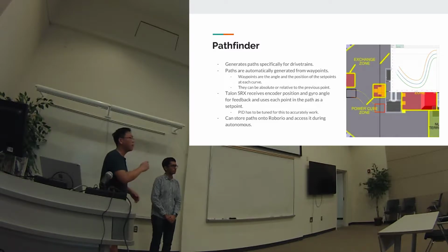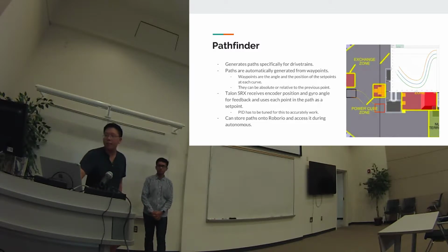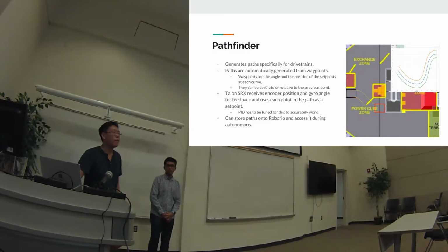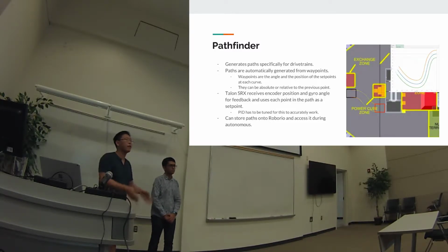And then one more: why did you choose that option instead of using the motion profiling mode on the Talon SRXs? Was there a specific purpose when you separated them? So with the motion magic stuff on the Talon SRX, we found it really good for one-dimensional systems, like just an arm, right, or an elevator that just moves in one dimension.